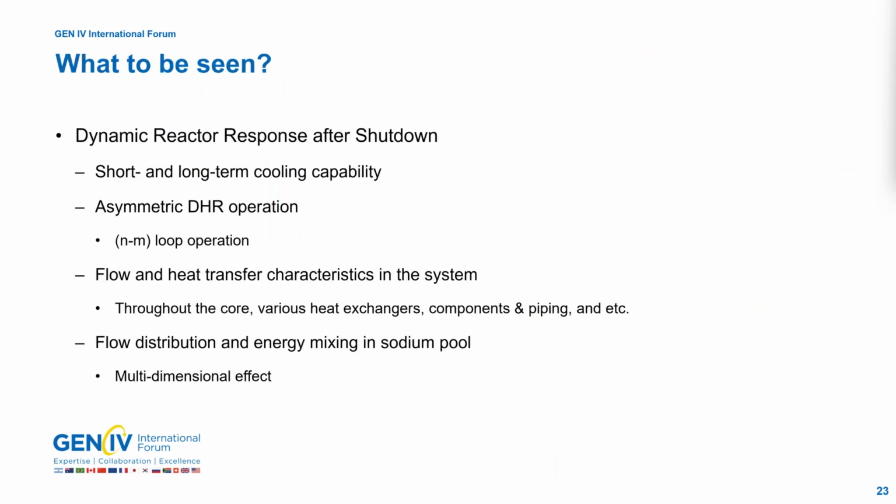So what is to be seen? The focus of this facility is as written in this slide. The short and long-term cooling capability will be examined. And also, asymmetric decay heat removal operation will be tested. Flow and heat transfer characteristics will be seen. And also, flow distribution and mixing in the pool will be seen. Next slide, please.